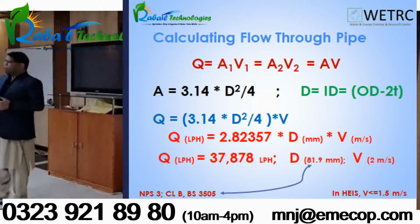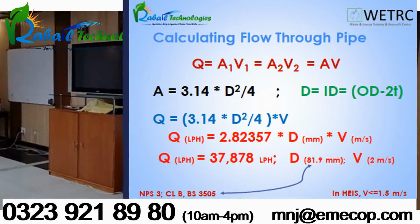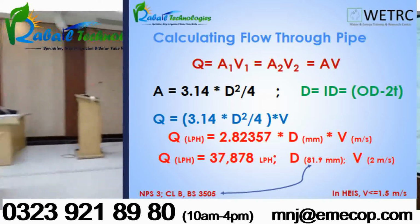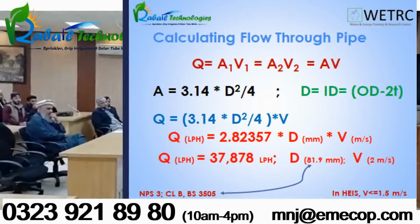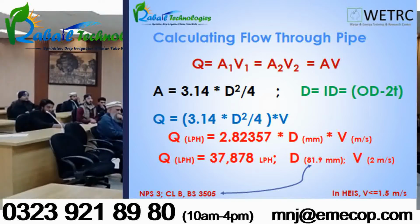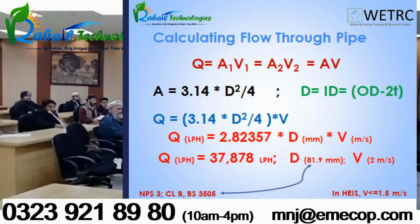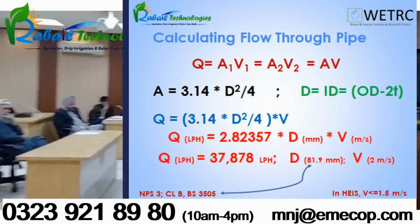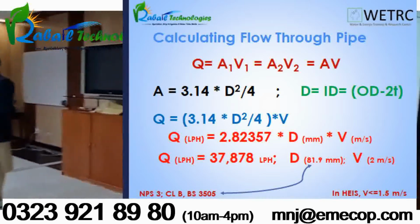Now see, if we reduce the velocity to 1.5 meter per second, the carrying capacity will be around 28,000 liter per hour. So with just a decrease of 0.5 meter per second, the carrying capacity of a 3-inch pipe will reduce by around 10,000 liter per hour.